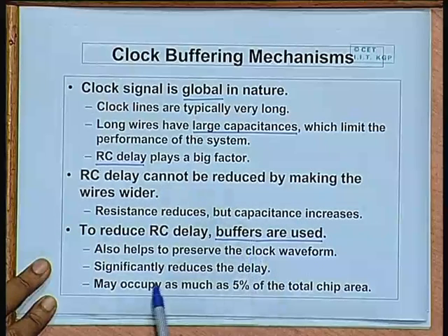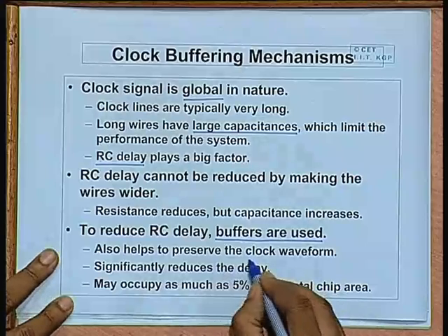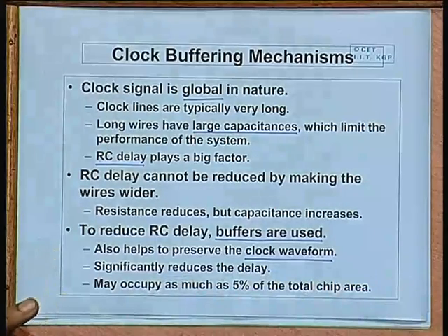Buffers serve two purposes. One is of course the reduction of delay, as I had mentioned, and second is that it will also preserve the clock waveform, because as it traverses over a distance, the rising edge and falling edge gets degraded. So, if you use buffers in between, the edges get sharp again. So, you again regenerate the clock signal. So, signal degradation is also controlled.